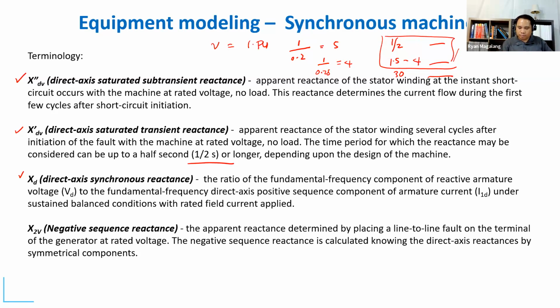That's just the explanation of why we have these different values of reactances for the same motor. It didn't make sense to me before though. Why? It's the same device. Why do you have three different reactances? That's the explanation. In order to keep the voltage at 1 per unit, when in reality it's the voltage that is decreasing in value. So, yep.